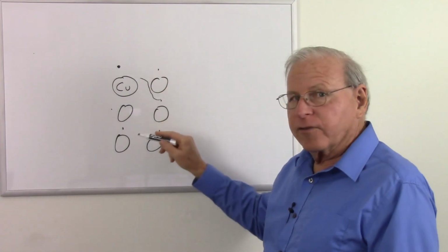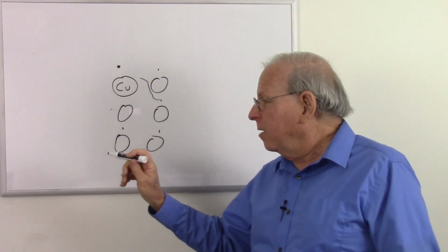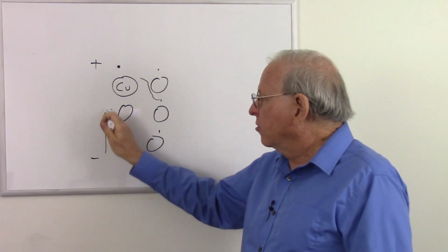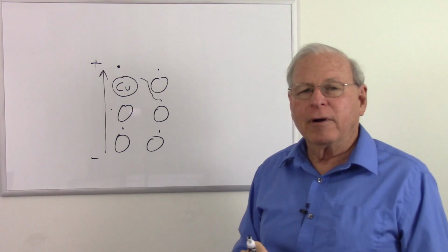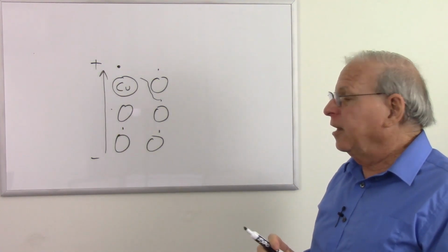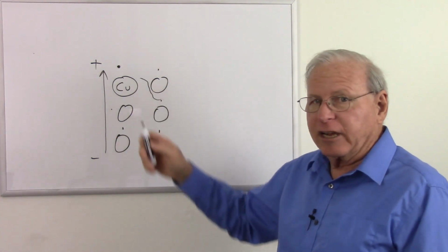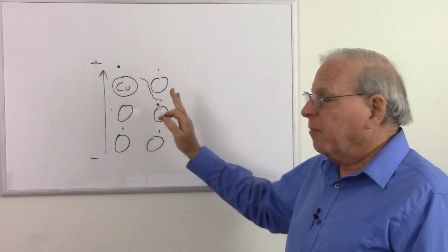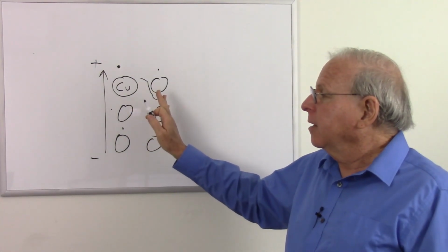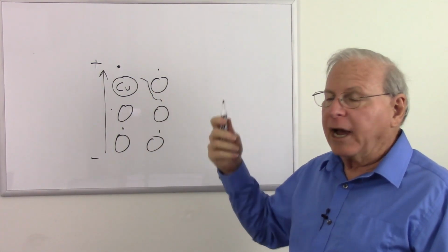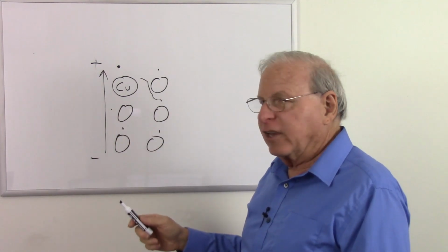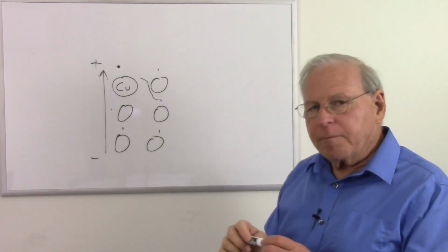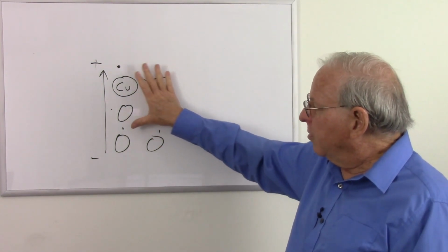And since these electrons are free to move around, it's very easy to put a voltage across there and push those electrons across. And so copper, like most metals, are good conductors. And your metals that have only 1 valence electron are your best conductors. Most of your metals have 2 valence electrons. Many have 3s. Aluminum, one comes to mind, is one that has 3 valence electrons and has less conductivity. So your metals tend to conduct electricity, and they form these metallic bonds.